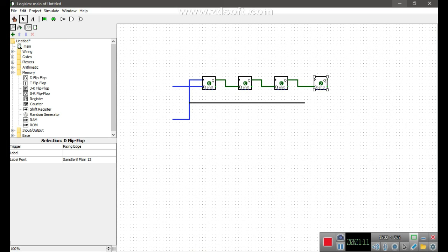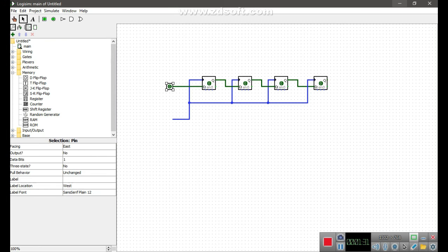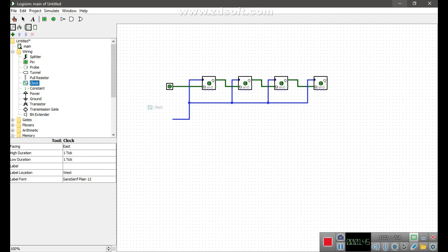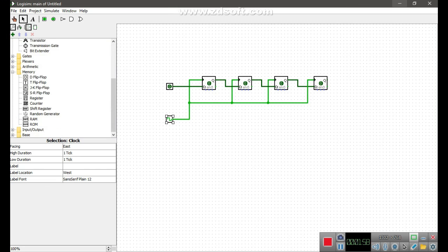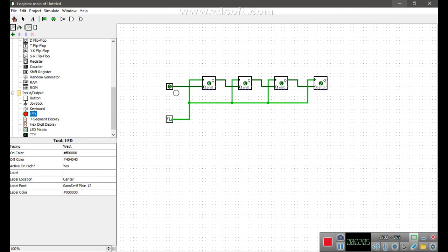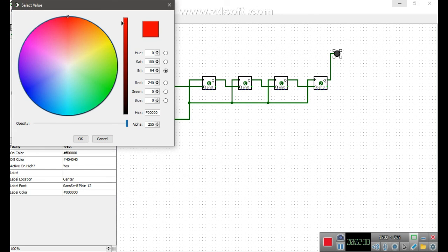A register basically consists of several single-bit D-type data latches, one for each of the data bits, either a logic 0 or a 1, connected together in a serial-type daisy-chain arrangement, so that the output from one latch becomes the input of the next latch and so on.